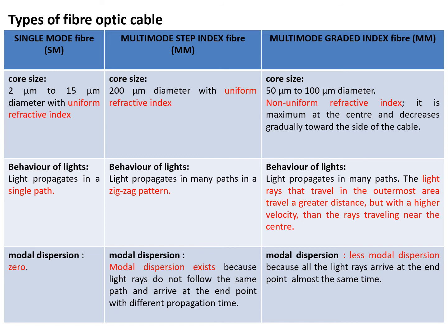In multi-mode step index fiber, light propagates in many paths in a zigzag pattern. Modal dispersion exists because the light rays do not follow the same path and arrive at the endpoint with different propagation time.